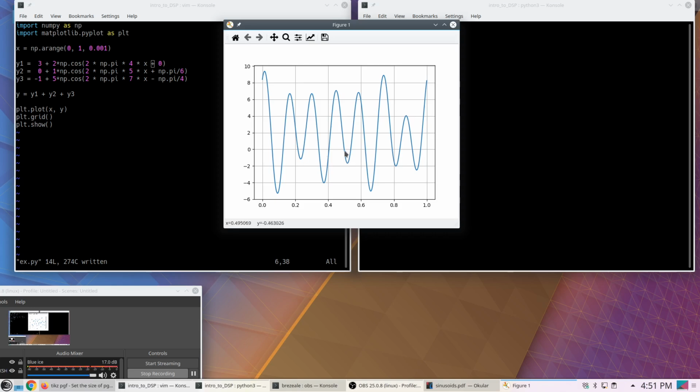So what Fourier's theorem tells us is that if this had been our original signal, we could decompose it into a 4 hertz, a 5 hertz, and a 7 hertz set of cosines. And I could have added sines in here if I want to, but I don't need to. Because really, what's the difference between sine and cosine? Well, they're just shifted by pi over 2.